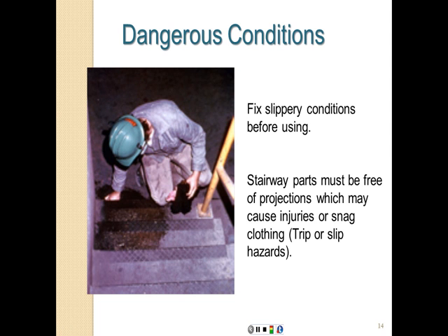We talked about the landing dimensions, 30 by 22 at least. We talked about the handrail height, 42 inches, plus or minus 3 inches. We talked also about if you have a door opening on the landing, then you should have at least 20 inches beyond the edge of the door. And finally, we talked about the necessity of providing a landing for every 12 feet, maximum of 12 feet of difference in elevation. You have to provide a landing.